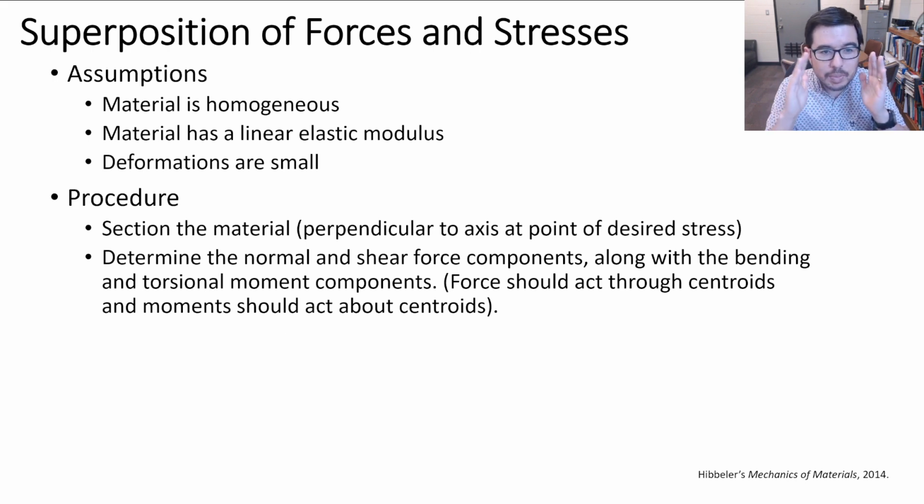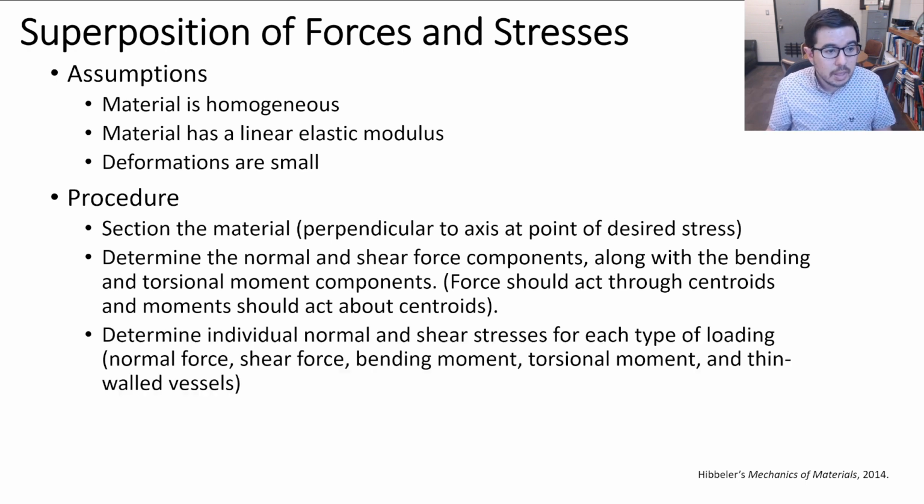I don't keep all these words exactly in my mind. But essentially the point is, let's take a look at that slice. Let's look at what the forces and the moments and the torques might be on that slice. And then we're going to figure out what the normal and shear stresses associated with these different types of loads are. And so we're going to be looking at the normal stresses due to normal force, shear stresses due to a shear force, or, again, we could have some type of point load force that twists and causes us to see some type of torque, which could result in a shear stress. And this will become more clear as we go through the examples, I assure you.